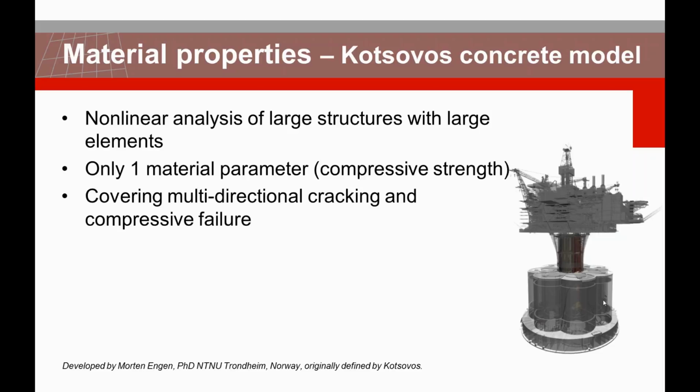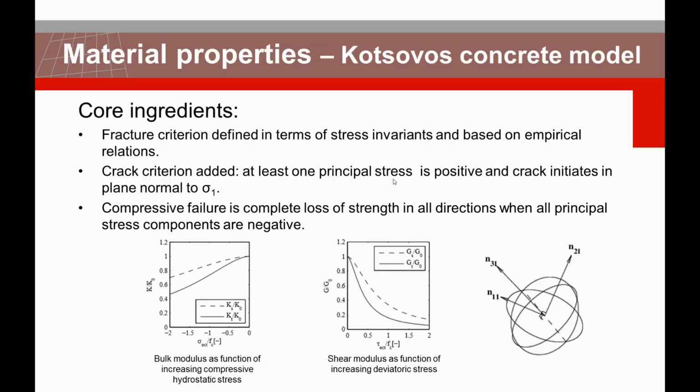The implementation is based on the multi-directional crack model. As input, the user only needs to define compressive strength. So nothing else. And for the results, you can nicely see the failure of the model. This model is verified and compared with an empirical model. And here you can see the relation of the bulk modulus and shear modulus, how they vary with respect to failure in the model.